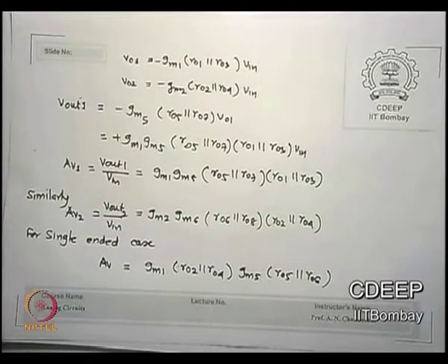How do I pass on that? The gate of that should get to the gate of that with a diode connection on the one side, so it will just replicate the currents in the next stage, and if you change the size you can increase it double or triple, or any amount of current can be pushed to the other side. So it is much easier to control the currents and therefore the outputs by just using the good current source as my one current source I create, and that I mirror everywhere wherever I want additional currents, is that clear?